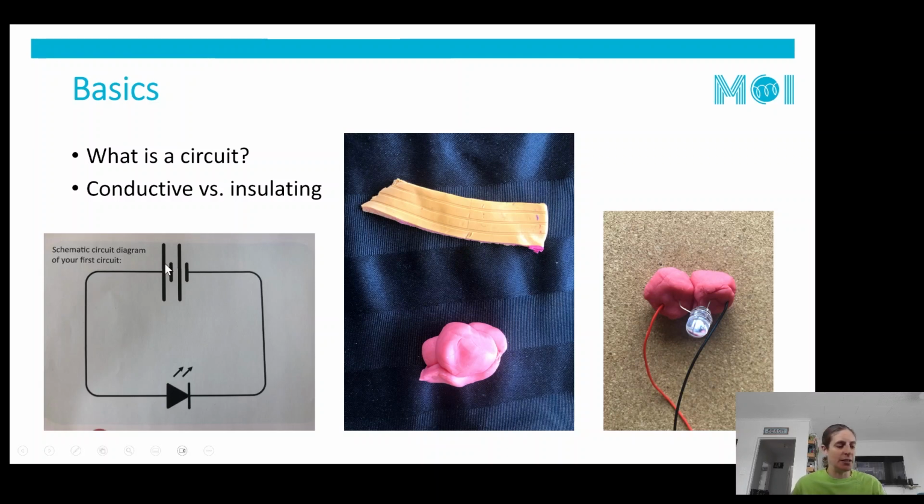Once you know what the circuit is, it makes troubleshooting a lot easier, as you are looking to follow the flow of electricity from the positive side through to the negative side, checking that each item is connected and that the electricity isn't skipping any items due to misconnections, incorrect connections, or what we'll talk about a little bit later.